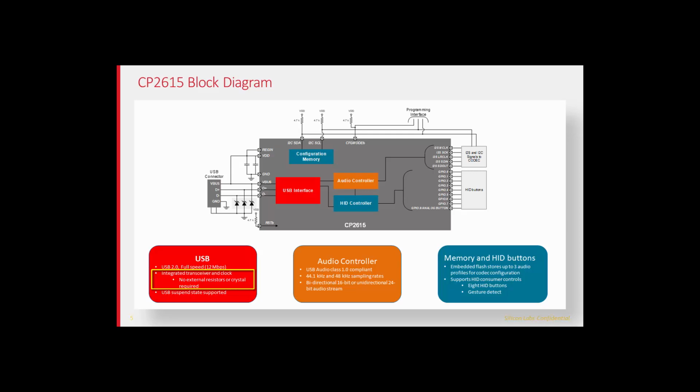What's being integrated? Yeah, that's a good question. I'd like to try to expand on it a little bit. First of all, let's address these hardware points of integration that you mentioned. The 2615, like all of our USB-enabled MCUs that we offer at Silicon Labs, supports crystal-less operation, so we can meet USB specifications without any kind of external crystal. Of course, that reduces BOM costs. We also have an on-chip regulator, which further reduces BOM costs.